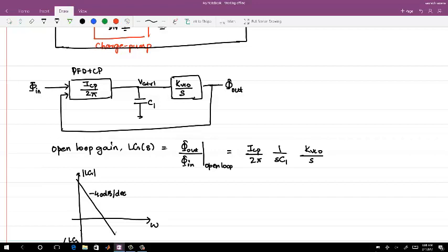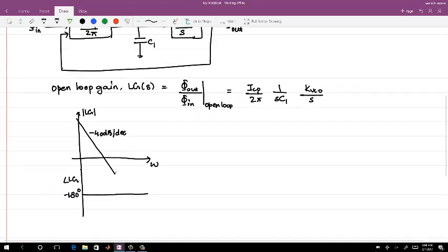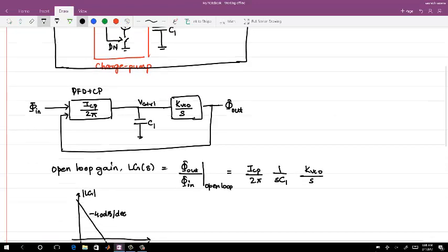That is not. No. So, okay, if that's the confusion. PFD output is phase error. The input phase error gives you the information, and what we are processing is the phase error at the PFD output. That phase error means the current proportional to that phase error is pumped, right? And current is pumped into what? An impedance.